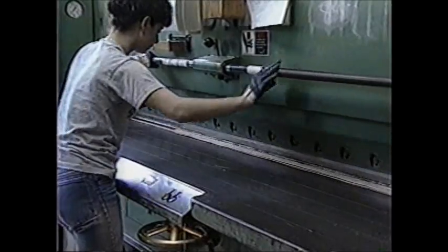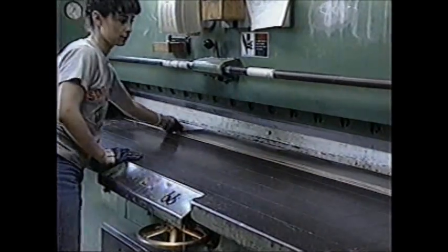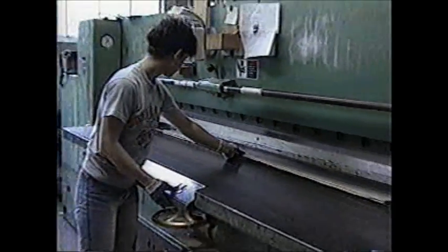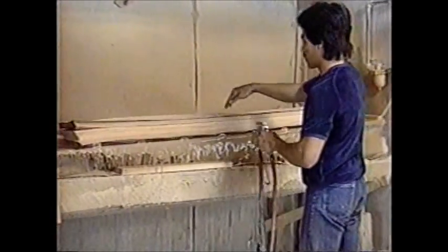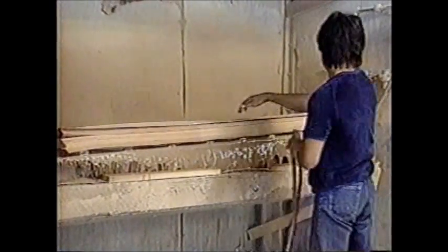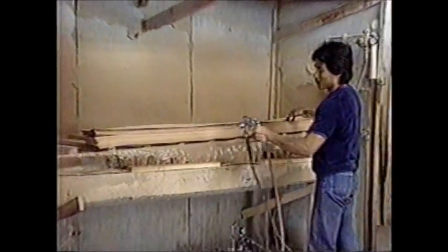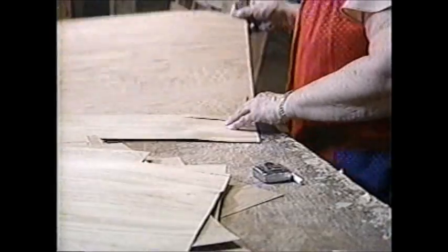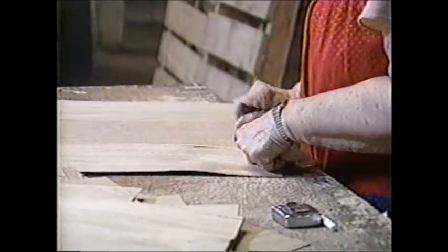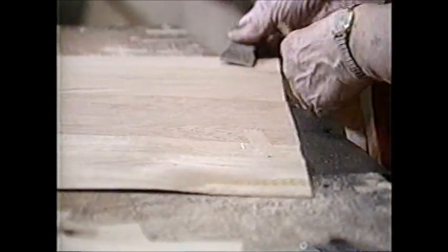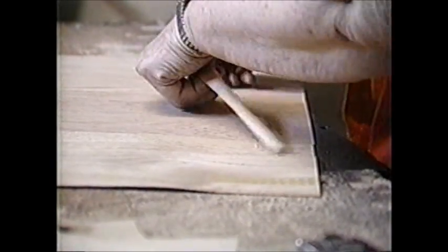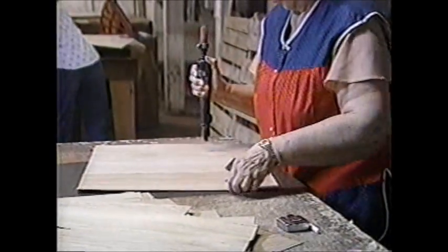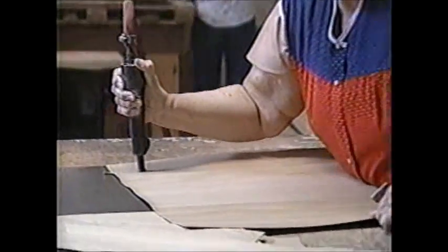Since sliced veneer rarely has parallel long edges, the sheets of veneer are trimmed to obtain parallel edges and appropriate widths. The veneer strips are joined into wider panels, a heat-activated glue is applied, and the pieces are then edge-glued in a splicing machine. If splits are detected in veneer pieces being prepared, the veneer back is strengthened with a very thin paper tape. The veneer face is then carefully worked with an air hammer to close and conceal the split.